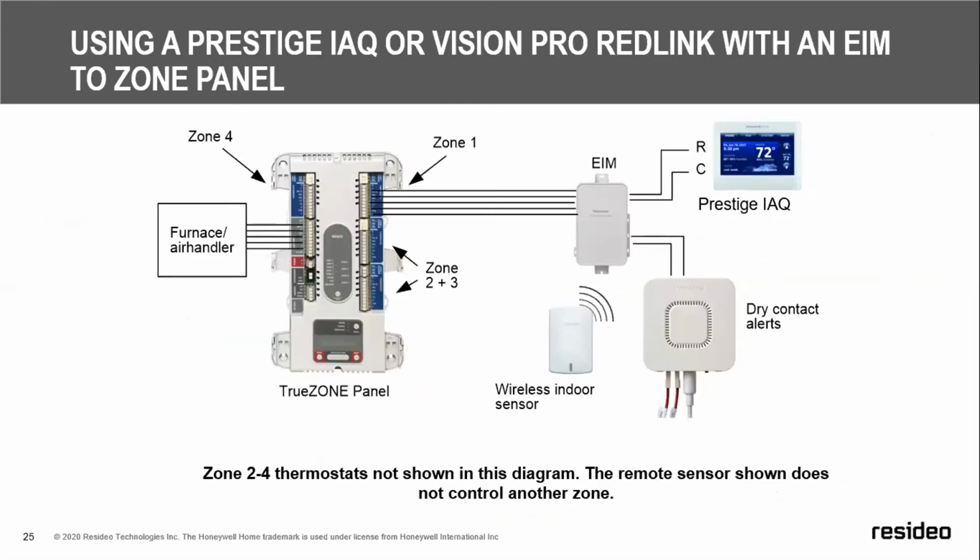Next slide, please. Okay, I was talking to you about some of the sensors that could be utilized with the system. You see one of our water sensing controls, and it actually has a cable. So if one drop of water touches that cable, it will close a set of contacts, which you can have put an alert on the screen of your thermostat. And if it's connected to the internet, it will communicate with you that way over the internet too.